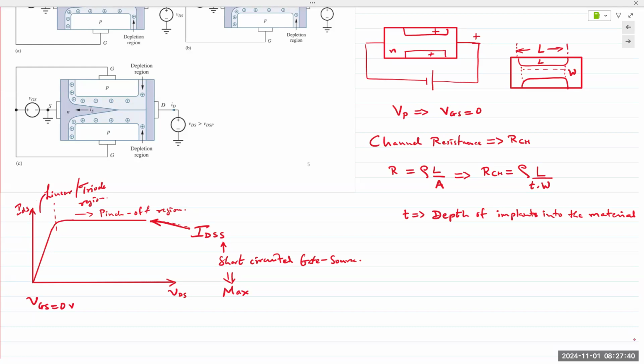It could run from microamps all the way to 10 amps or so, quite a large variation. Pinch off voltage can run from 0 all the way up to like 20, 25 volts or negative 25 volts. That's the range we are talking about for these JFETs.